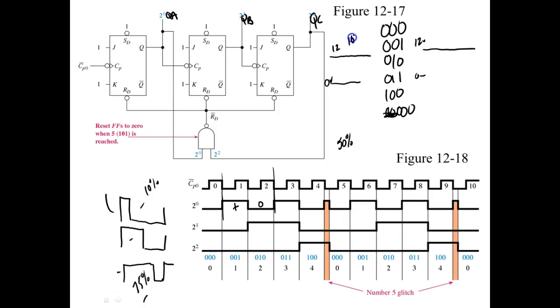This is a duty cycle of 100% because it's high 100% of the time. We have no pulse anymore. When it's sitting down here, this would be a duty cycle of 0% because we get no voltage out. So just looking at that, which one of these would give me the highest average, 75% or 10%? 75%, right? Doesn't it make sense?